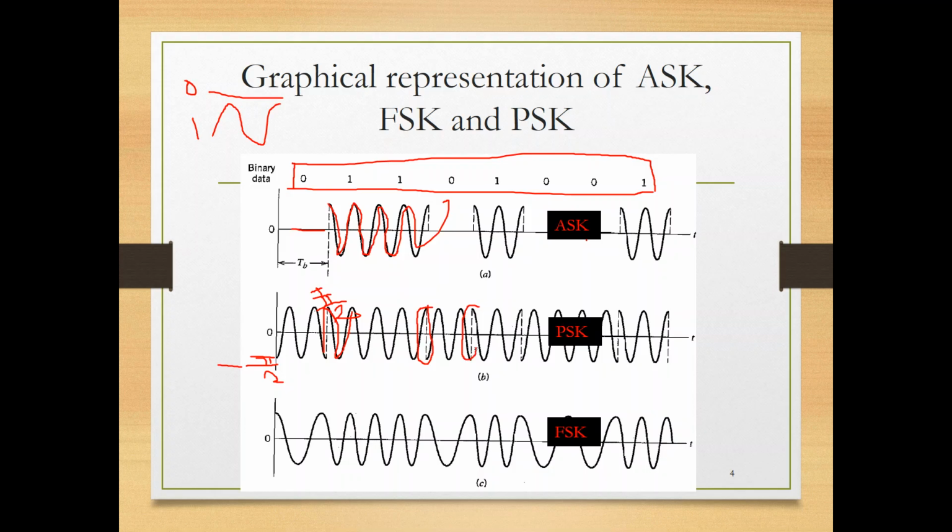He says when you have a jump in the amplitude, not a smooth transition, you create interference. You create out-of-band emission. Your symbol, if it was supposed to be like this, then it becomes like this, interfering. Your symbols are back to back, and if they interfere like this it becomes interference. You will not be able to detect the signal.